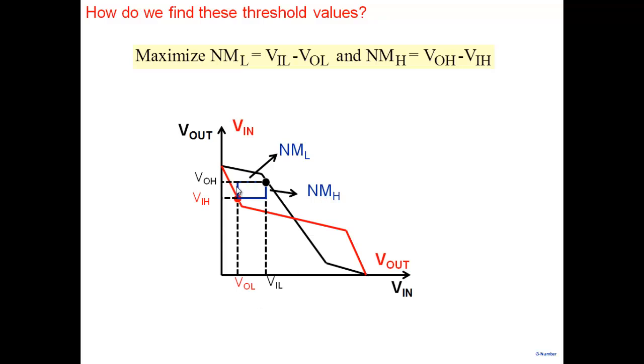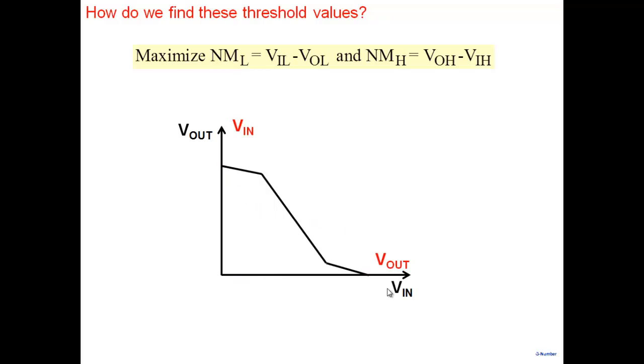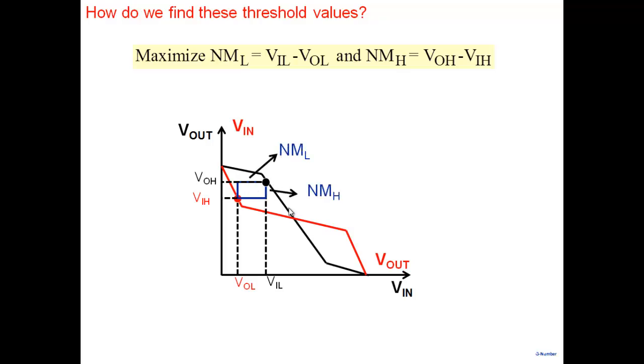So what are we saying here? What we are saying is the following. You have your VTC. Draw another VTC with this flipped, V out and V in. Flip it here like this, right? Right now it's arbitrary. Define your VOH and define your VOL. And once you do that, these values get defined. Make this box here. Then this is NML and this is NMH.